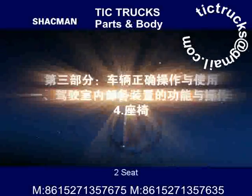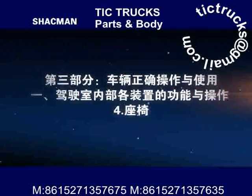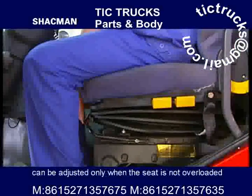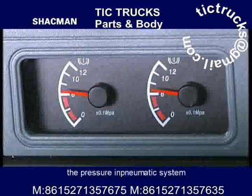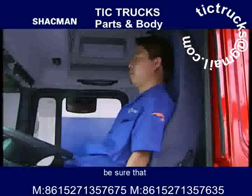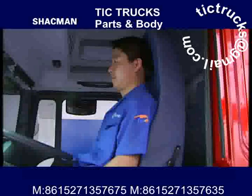2. Seat. The driver's seat falls into air suspension seat and hydraulic seat. The air suspension seat can be adjusted only when the seat is not overloaded, the pressure in the pneumatic system is 7 bar and the vehicle stops. When adjusting, be sure that the engagement sound of the seat locking device is heard.